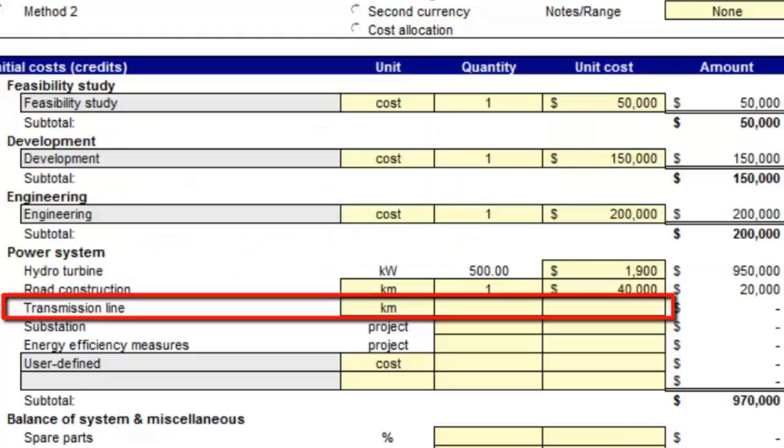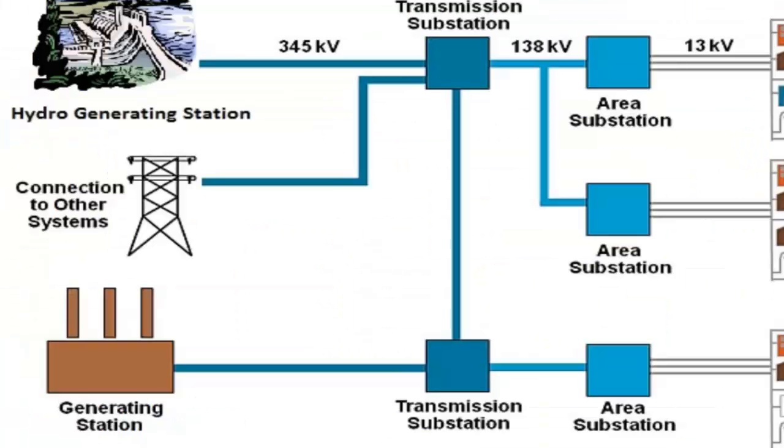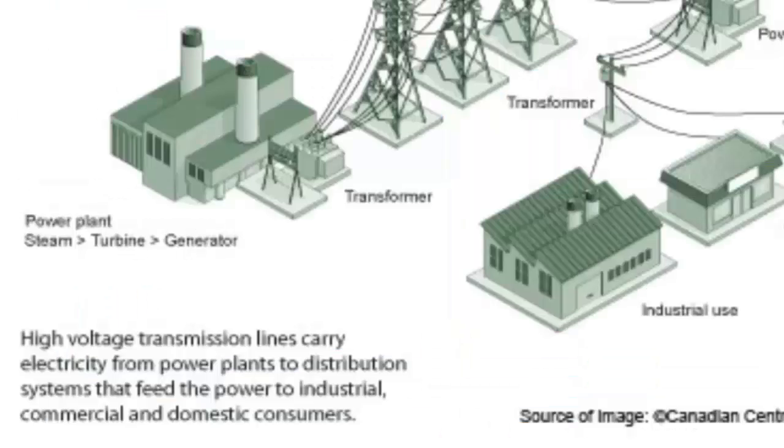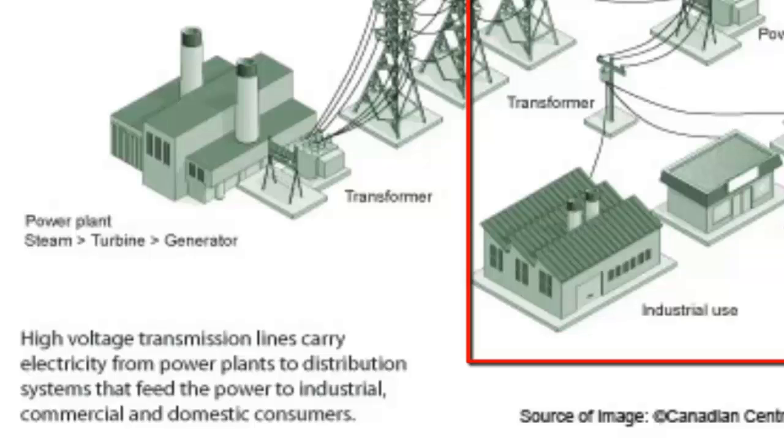Distribution is the local electrical infrastructure through which electricity is delivered from the high voltage regional system to the end-use electricity consumers. Distribution is generally characterized by short-distance lines, low-medium capacity transformation and switching stations, and typically a low degree of meshing of lines and stations. Most end users of electricity are supplied from the distribution system. The distribution system is radial in nature. Loop feeds are primarily reserved for areas of high density.